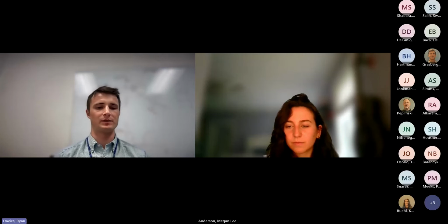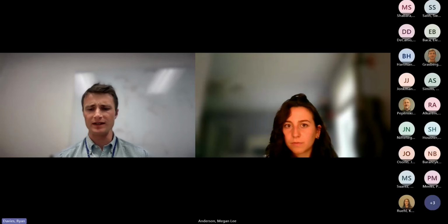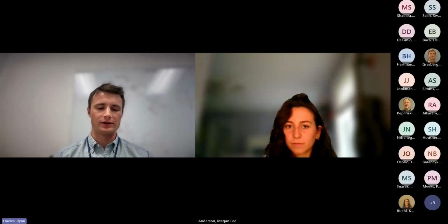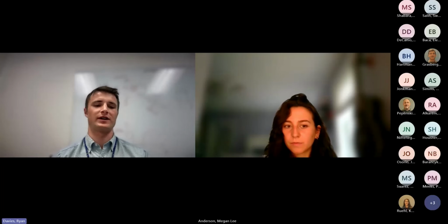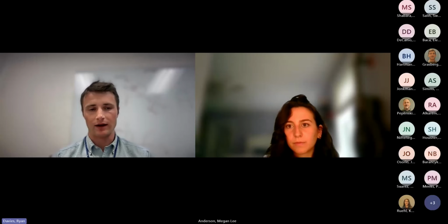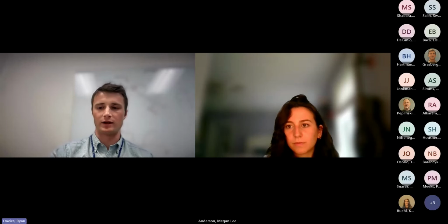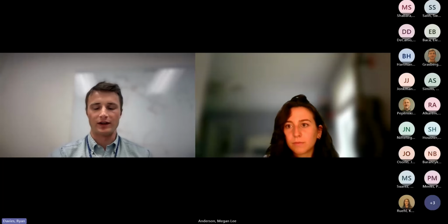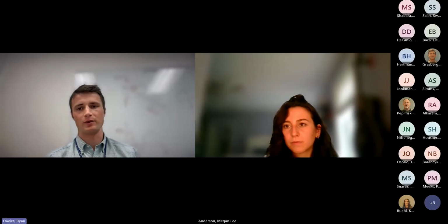And so if you want to be using MoorDyn for that, what you can do is export your initial state of MoorDyn to a binary file. And then you can load in that initial state every time that you call MoorDyn. So instead of having to initialize MoorDyn 50 times or 100 times or whatever you're doing your optimization for, you can just directly load in that pre-initialized state and go from there. Noting though that if you are changing your mooring system, you're going to have to reinitialize because it's going to have different properties.